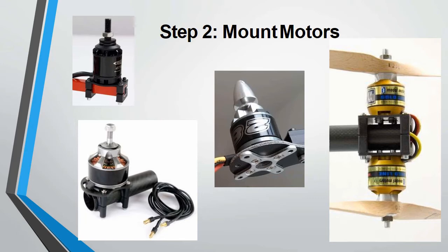When looking for the motors, you should know that multi-rotor drones produce greater speed and ensure a stable flight, as each rotor works with the other thrust points. I have explained this earlier also. So for the propellers, we suggest buying the metal 9-inch props at a very affordable price in the market. These are durable and won't bend so easily if the drone hits something during flight. However, if you want better performance, it would be better to go for carbon props. If you want good performance, we recommend getting any of these.